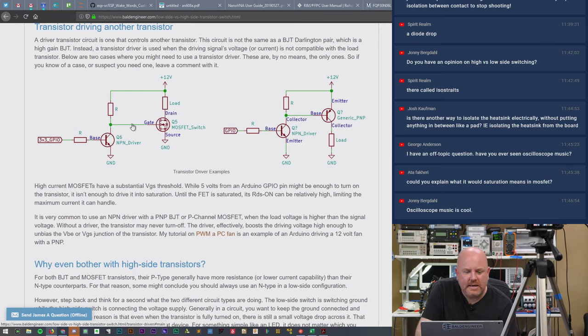So the problem is, I think some people get concerned because, if this turns off, so that's 0 volts. This turns off and becomes an open. So now we have 12 volts here. If you turn this on, this shorts out, this becomes 0 volts. So then we see 12 volts drop across the resistor, which means the gate turns on.